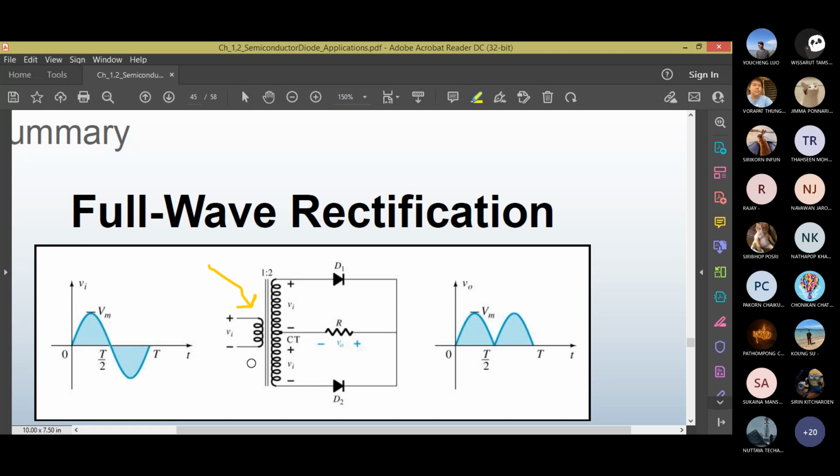The primary side voltage is V1. Secondary side voltage is V2. The ratio goes like this: N1 over N2 equals V1 over V2. If you want to find the current, the ratio is N1 over N2 equals I2 over I1. For the current, the numbers reciprocate. So here it is showing 1:2, which means it is actually a step-up transformer.